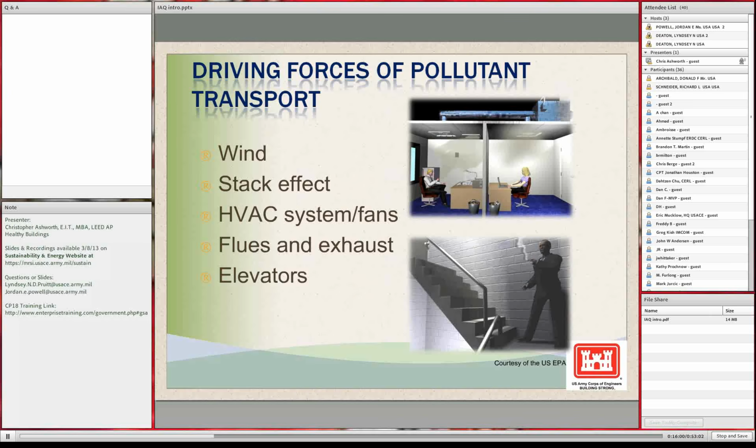Another effect in a building is what's called a piston effect. It's when elevators are moving up and down and actually moving the air because there are large cabs moving up and down. So you can take a contaminant that is from, let's say, a laboratory on a low floor. It can easily be transported up and it can easily be transported down. So again, proper pressurization and HVAC maintenance and design can prevent all of these issues. It's just having those issues brought to everyone's attention early in the development process and/or in the management of the building.